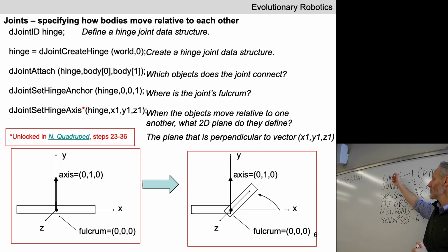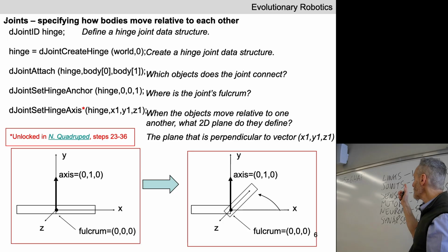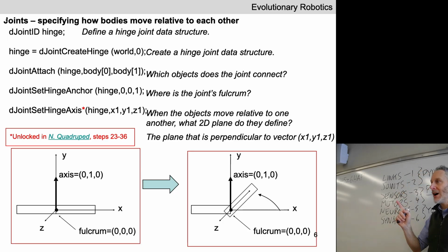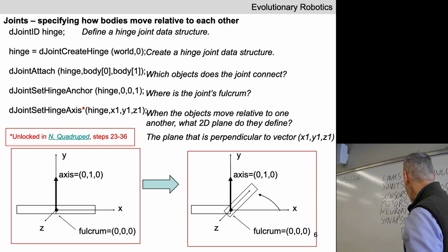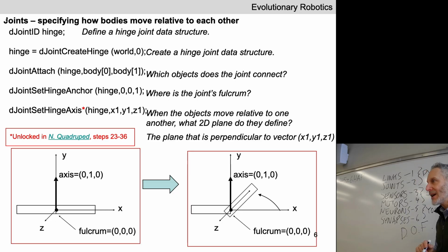We'll come back to specifying the geometry of links in a moment. We're kind of doing things in a weird order today. Joints you've already come into contact with, no pun intended. Joints connect links together, but more truthfully, what they actually do is remove degrees of freedom. As roboticists, we're going to use this term a lot in this course. What is a degree of freedom?